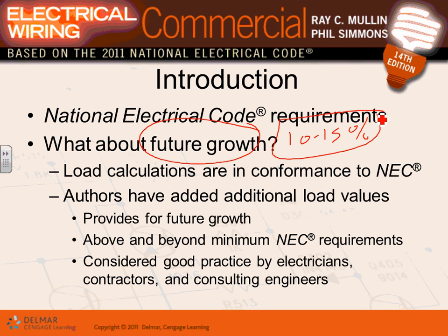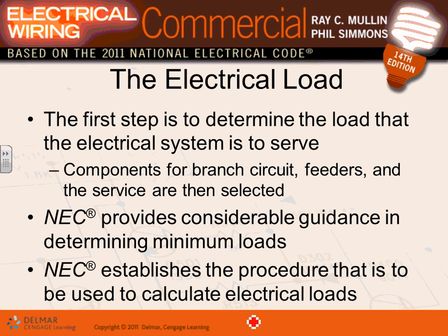Provide future growth above and beyond the minimum requirement, good practice and efficiency, consultant engineer, guys. So if the code says what we do most of the time is a good design. Like I said, an optimum design is trying to find the balance between too much and too little, right? You need a good design at an affordable price. That's always the balance. So with the NEC code book, guys, we typically go higher than NEC because that's the bare minimum. NEC is the bare minimum.